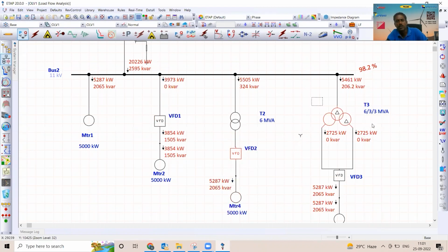And of course, if you're going for a 12 pulse variable frequency drive, there is no other go. You have to definitely go for a 3-winding transformer. I guess that gives some base idea of how to select the transformers. Once the motor has reached its rated speed, if you're bypassing the variable frequency drive, please don't go for a variable frequency drive, just buy a soft starter.